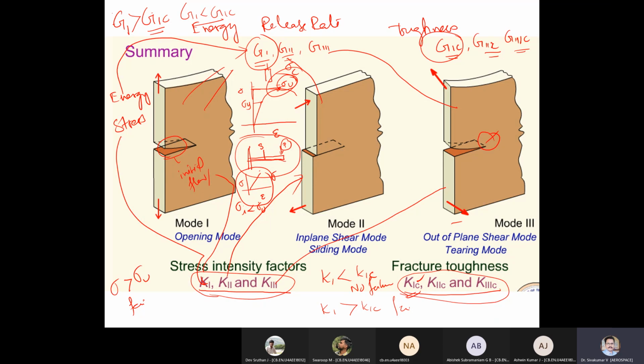Similarly for energy, you find these values for every material. This is the laboratory tested toughness value, the critical value. So the real, on-site value should be less than the experimentally tested ultimate values. If it is more, failure will take place. This is how the design process goes. I hope you understood.